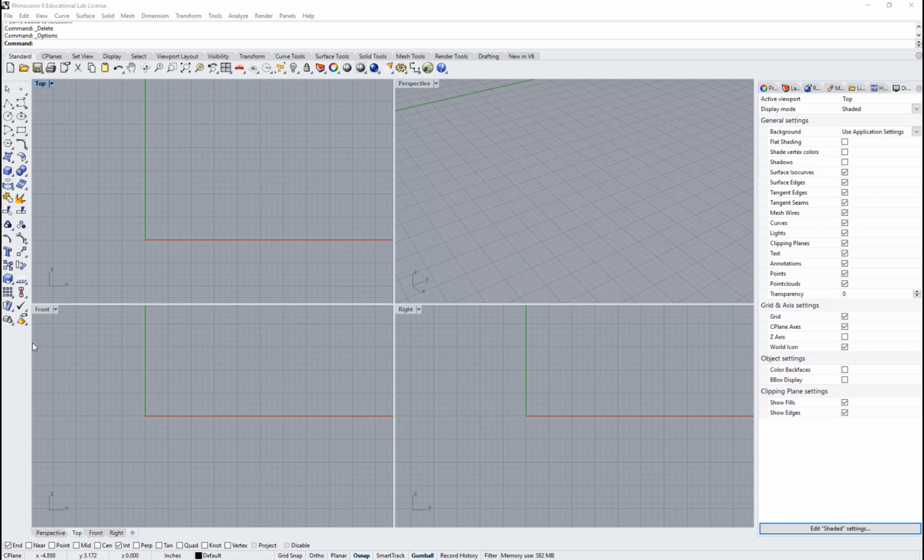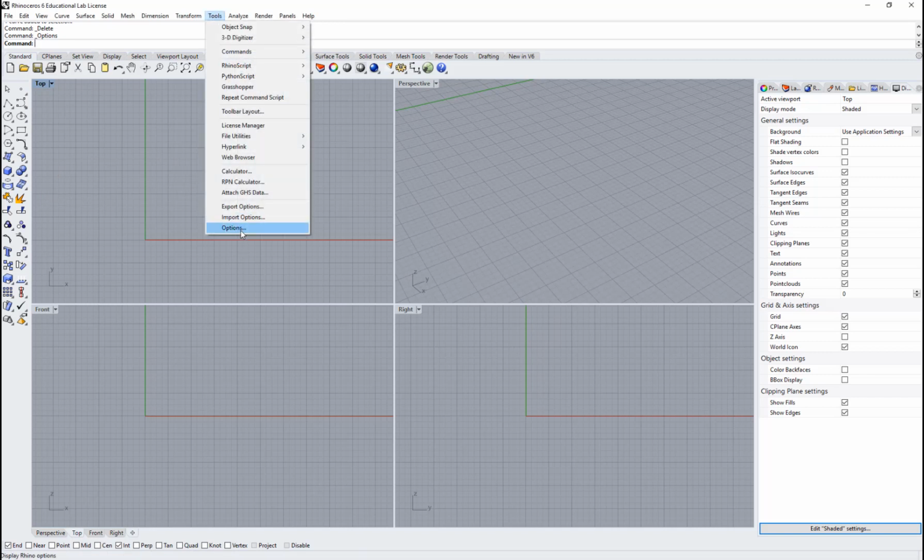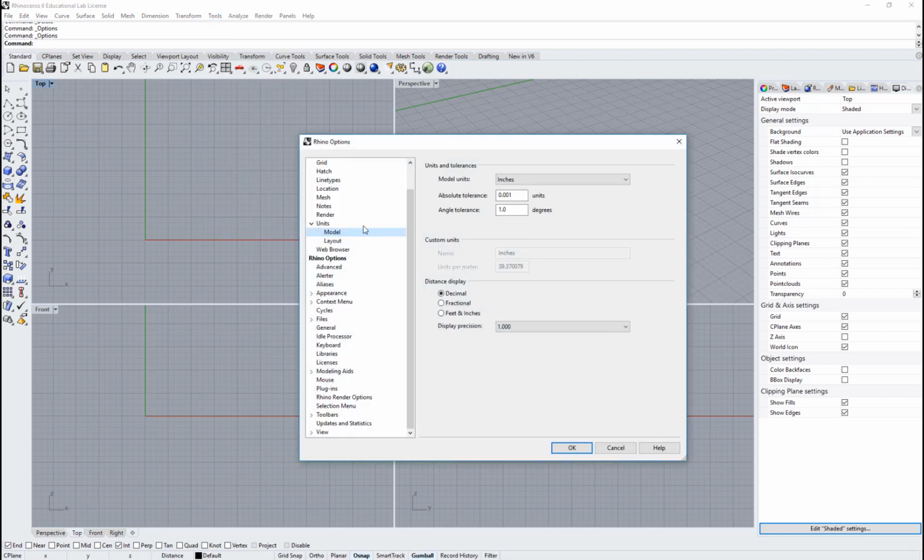In this demonstration, we'll create a simple polygonal form. In doing so, we're not going to create it to scale, but at actual size, since this is basically a shape and not a real object itself. We'll apply the object scale to it later if we'd like to. To start off, let's get ourselves all in the same units, and the units should be set to inches, and the display, I'm going to set mine to feet and inches, as well as the layout, feet and inches.